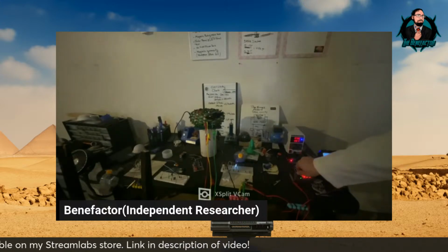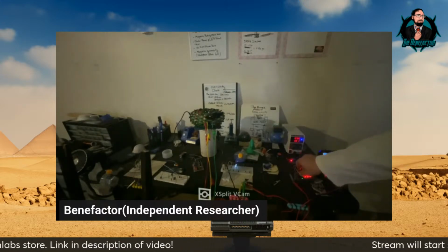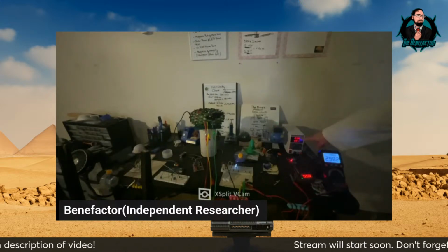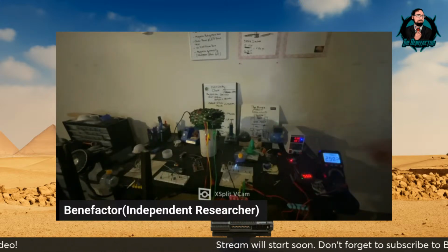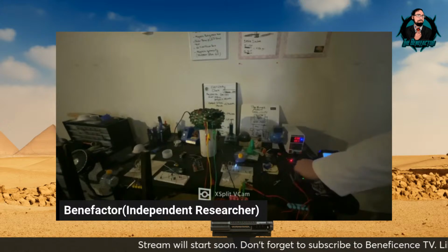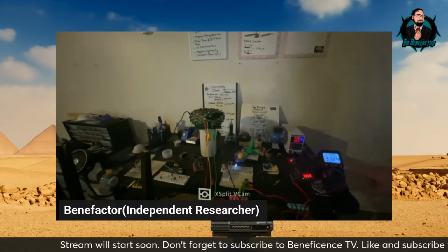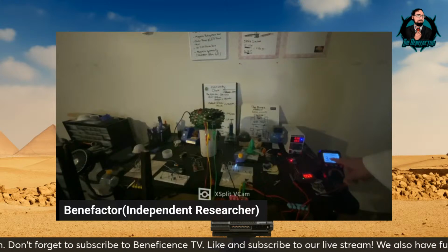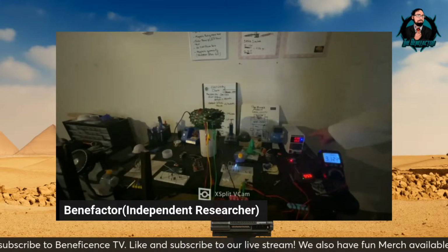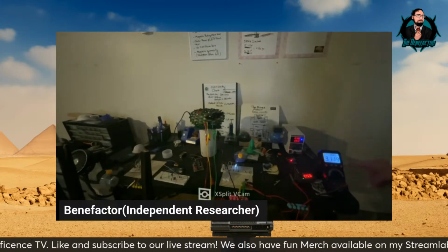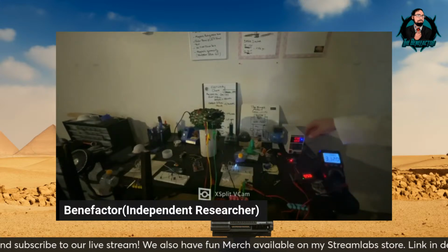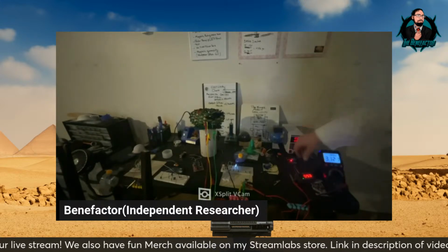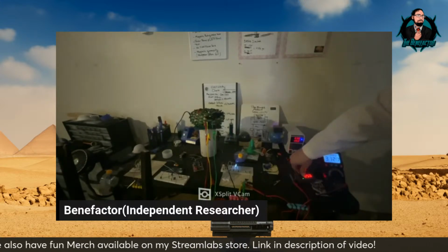When you say it went down to 3, what are you referring to? We got 3.8 volts going in. And right now, when we're at 50%, which seems to be our max duty cycle threshold, it's at 3.1 versus 3.8 on the input. So it's close. But as soon as we go above 50%, the voltage on the output takes a crap.